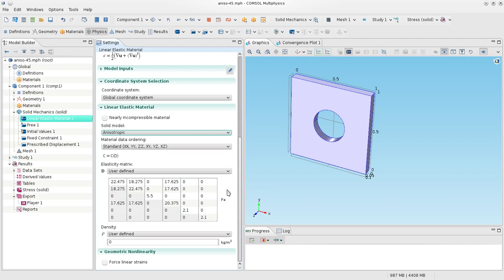Okay, so on the right we have strain as a vector 6x1 multiplied by the stiffness matrix, spits out as a result 6x1 stress as a vector. Okay, so this is normal coupling, this is normal shear coupling, this is shear normal coupling. Again, you observe the symmetry that we're supposed to have. Okay, so this is 4-1, this is 1-4, this is 2-4, this is 4-2 component, they're the same. Okay, symmetry is still there, and this is shear coupling.